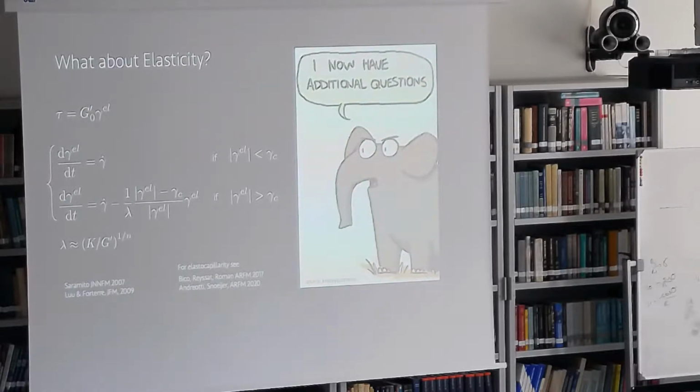You can do the calculations based on relaxation time and experimental time scales, and that typically gives you a Deborah number that is not significant. But it's very naive to say that because the Deborah number is 0.1, it's not important. It could be important. So the honest answer is we don't know. I think there is a lot of room, and it's a very important question. That's the direction we want to go: repeat the exact same thing with elasticity included, and then see the difference.